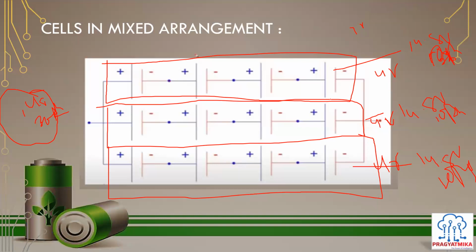But for the NMC specifically, because this is what we have considered here, because in the mixed arrangement it is the NMC that is used most. So in that, we use the voltage as one of the parameters for knowing the status of the cell. If we have the measurement of each and every cell, the more accurate balancing our BMS would be able to do. Am I right?